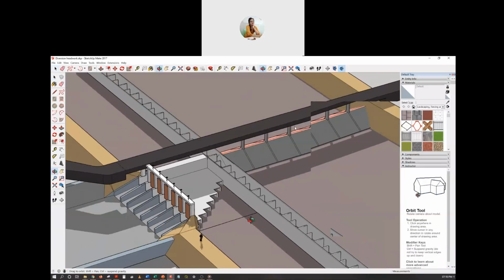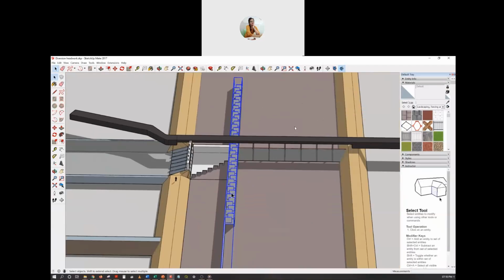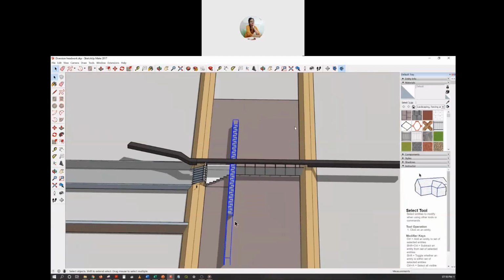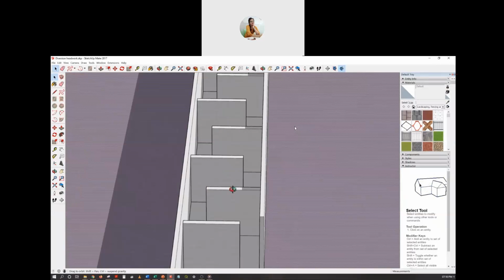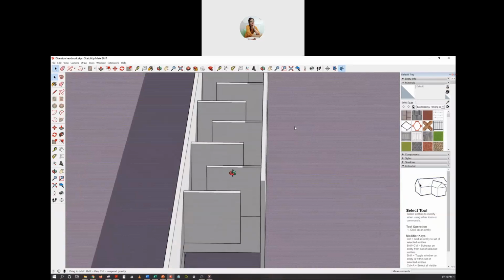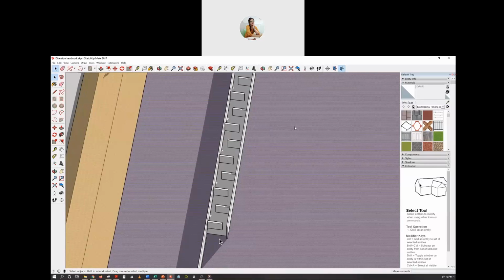This portion is called a fish ladder. It's a long channel connecting the upstream and downstream of the weir, and it is provided with these kind of small walls projecting from both sides of the canal. What happens is, water when flowing through this will have to take a very zigzag path like this, and therefore its velocity will be reduced.